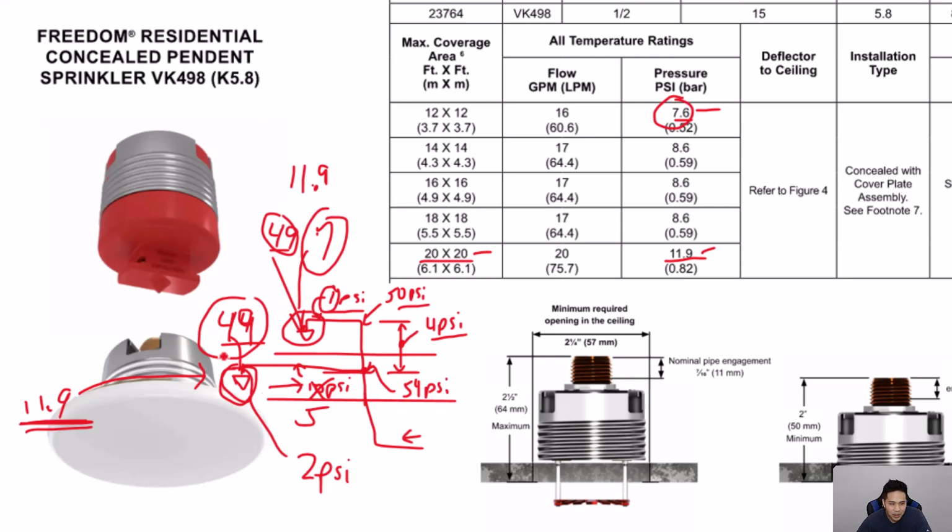So this is a very long way of stating that it's not always necessarily the case that the highest sprinkler head that is furthest on that floor level or that height level is going to be the most hydraulically demanding sprinkler head.